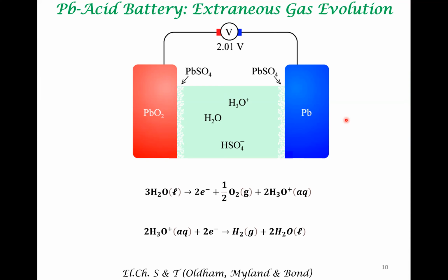One quirk of nature which made lead acid battery rechargeable is that lead sulfate is not soluble in the electrolyte. Another useful quirk of nature is that these two electrodes are very bad at oxygen evolution and hydrogen evolution. In the sense that if you use these as electrocatalysts for hydrogen and oxygen evolution, these are poor electrocatalysts.